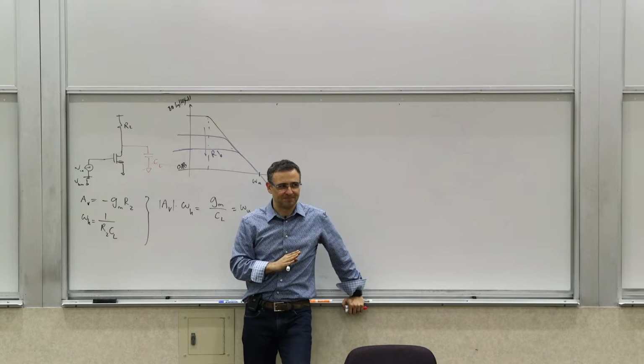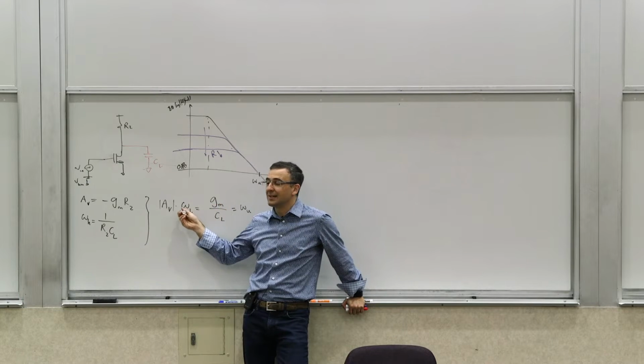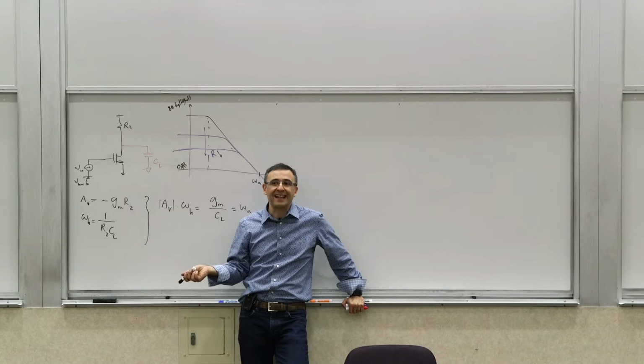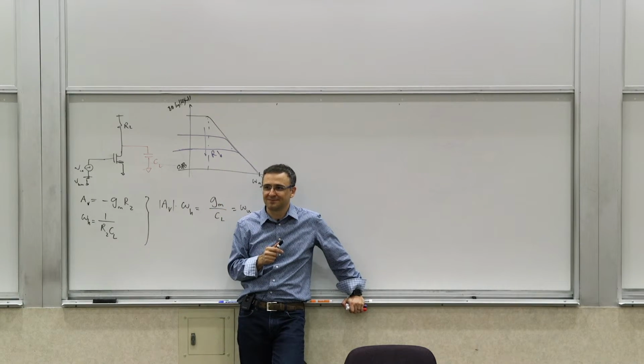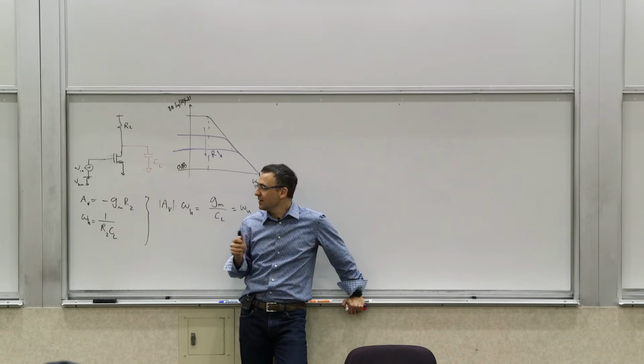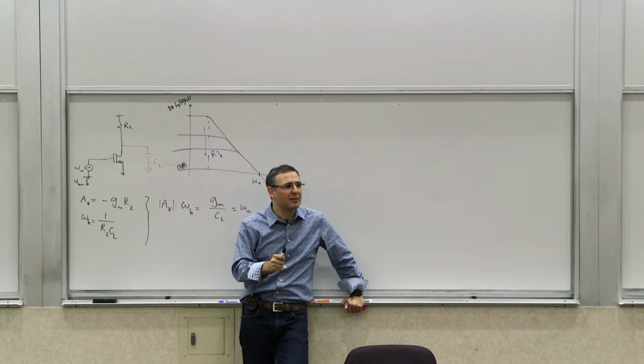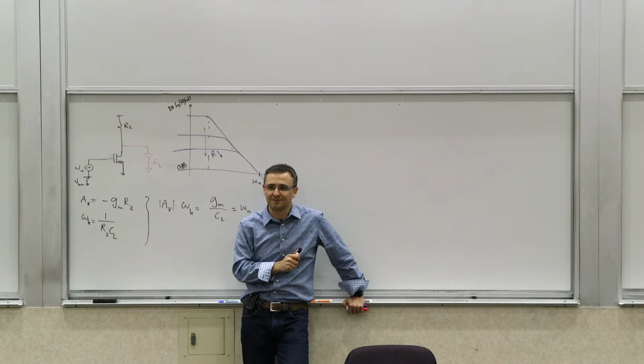Not exactly. The real trade-off, as we will see later on, and I'm going to give you a little bit of preview, is between the gain bandwidth product itself and the delay, or the latency of the system. And this happens in a lot of different systems. It even happens in mechanical systems too. If you want a large gain bandwidth product, you can achieve it by allowing for a larger delay.